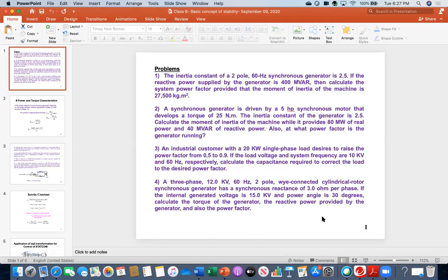So therefore, Lakshmi and Sindhuja, once you get the P value 30 megawatt and Q value 3.96 megawatt, then just use the power triangle, like tan theta is Q over P. Yes, Dr. Ali, I got 0.99 for the power factor. Oh, okay, that would be great.